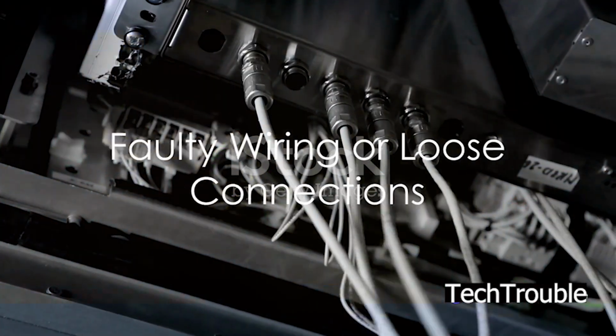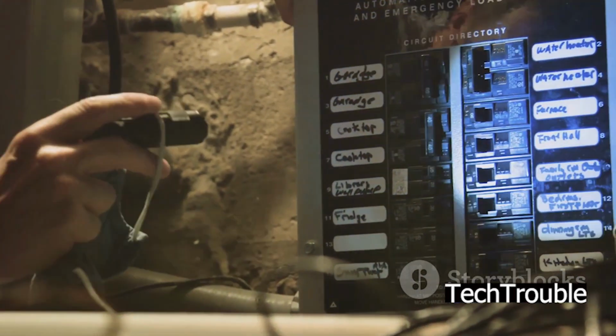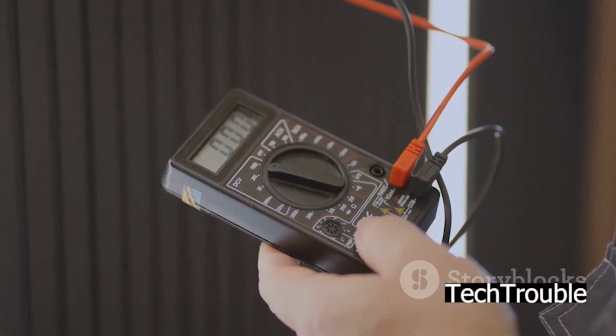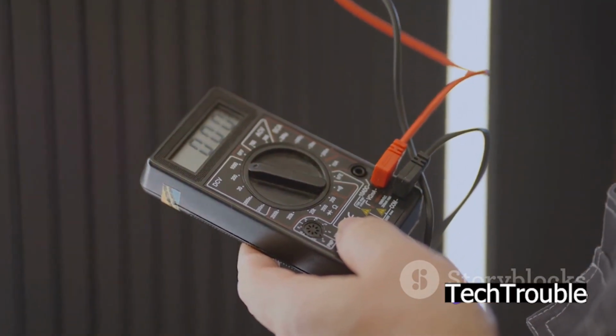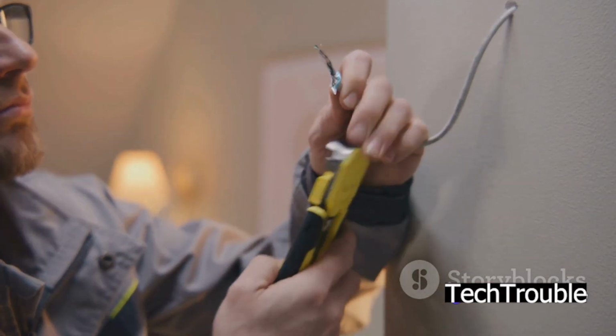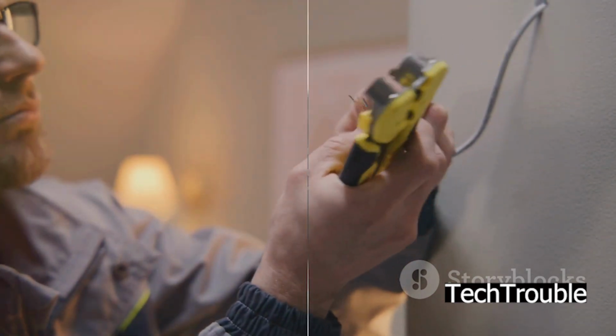Now, let's move on to faulty wiring or loose connections. Loose or faulty connections can interrupt power or cause the UPS to malfunction. Ensure all power cords, input-output connections, and grounding wires are securely plugged in and free from damage. If you spot any loose cables or signs of wear or fraying, reconnect and replace as necessary.